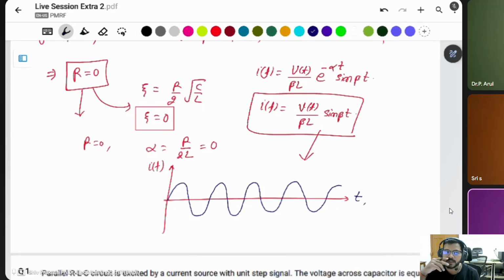Natural commutation means if you work the thyristor in an AC circuit, where the sinusoidal current has plus and minus halves, the negative half blocks the thyristor and the thyristor is off. Then after that, it is on in the next cycle. But a DC source is constantly on. Then how can you turn off the thyristor?